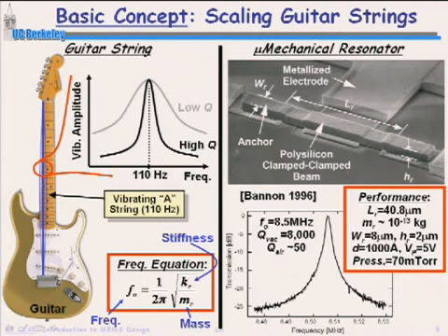To compare this to transistor circuits, we talked about this last time. If you're using integrated circuit transistors and designing using analog circuits, what do you have that can create resonators? You have capacitors, which are quite high Q devices on chips. Capacitors can have Qs on the order of 10,000 or so, if you've got good ones in an integrated circuit technology. The problem with integrated circuits is you don't get good inductors. To make a resonant circuit, you need both a capacitor and an inductor. And the inductor in a typical integrated circuit technology is going to have a Q on the order of 5, 10 if you're lucky.